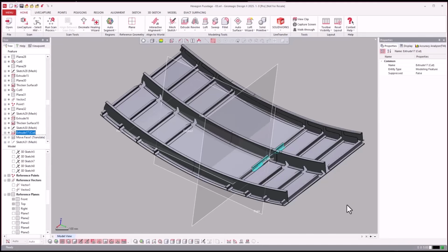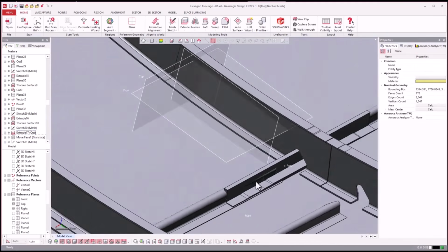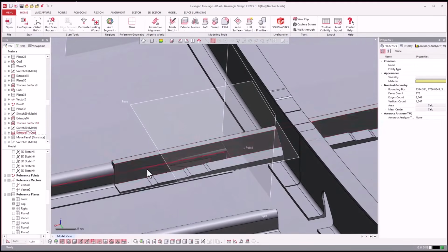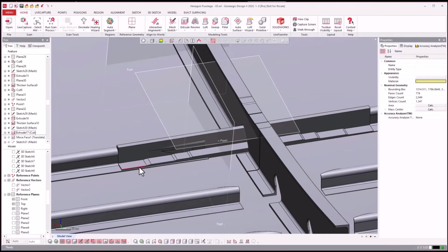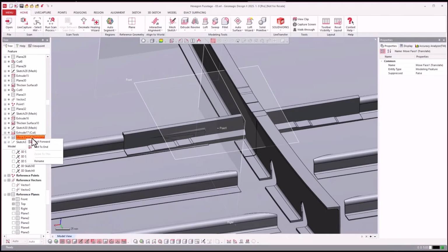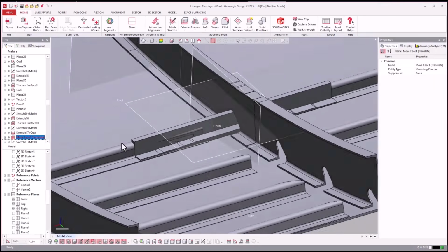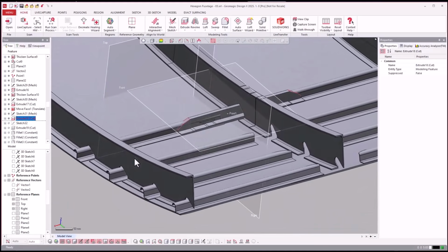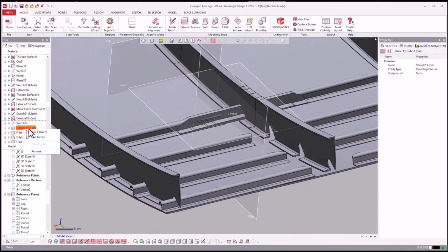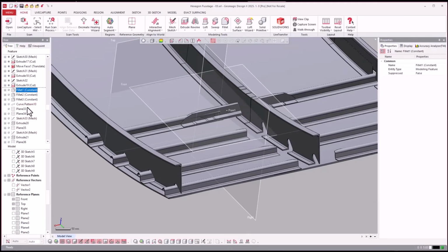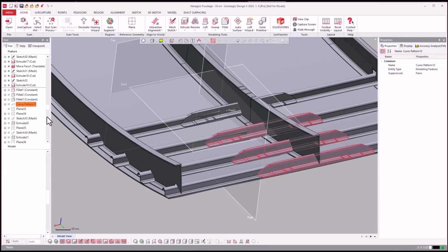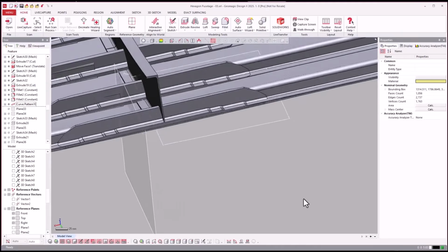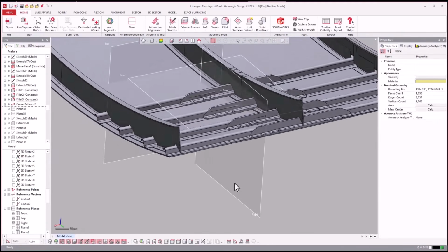So now we come back and there are these joining brackets, and we fit those. These joining brackets have multiple steps here because it's a bracket that goes across, then it cuts away. Did a move face there. Cut it from the side. Cut it from the top. Apply fillets and then pattern. So you see that bracket there.